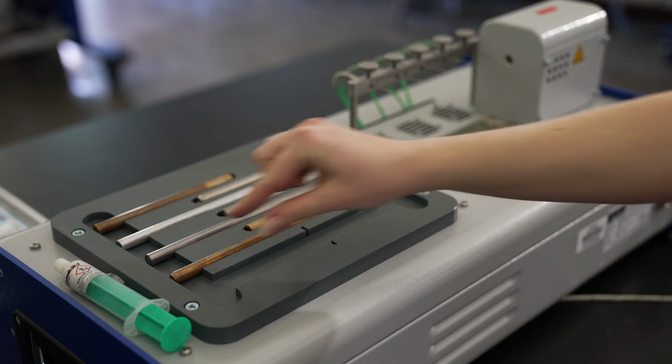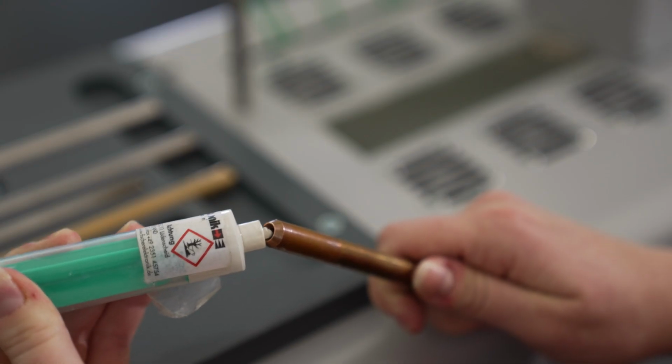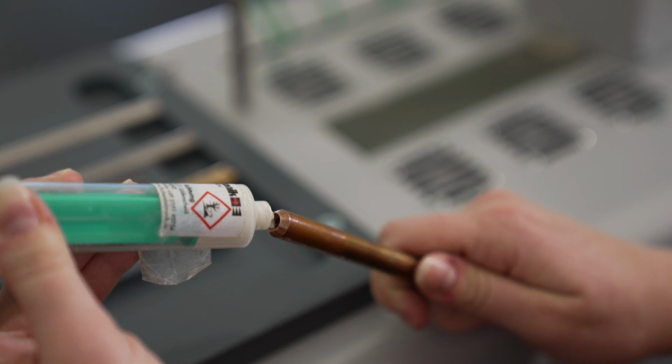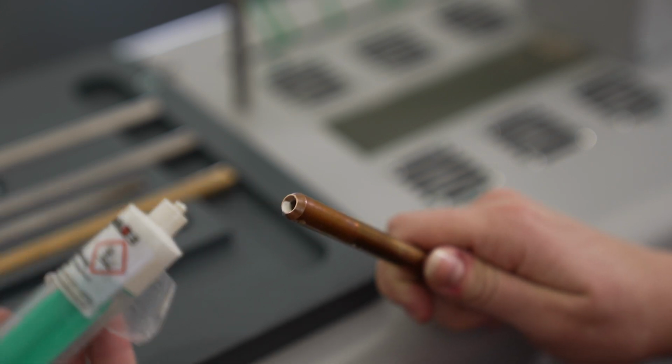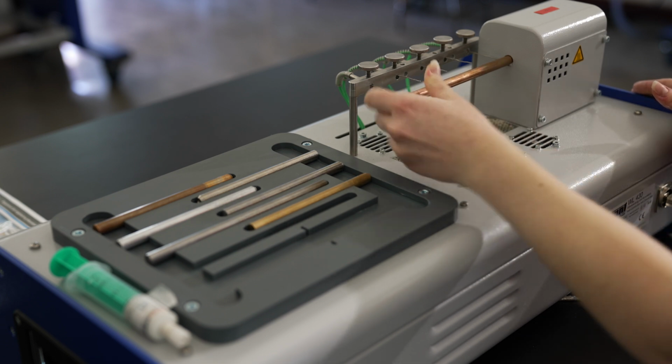In this video, we will describe activities which utilize the device WL430 heat conduction and convection to study heat transfer in fins. Before operating the machine, make sure to wear safety goggles and adhere to laboratory safety rules. Select sample as per guide. Use a very small amount of thermal paste if necessary. Insert it into the heater housing port. Rotate clockwise until an audible click is heard.